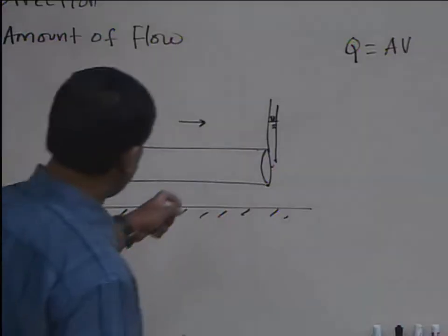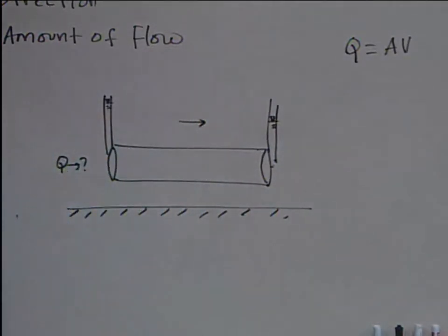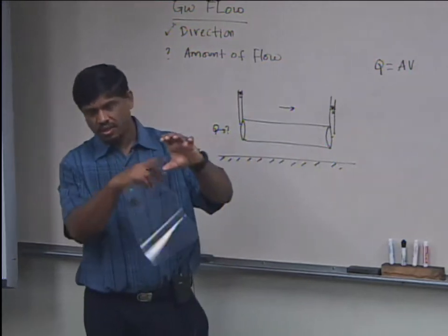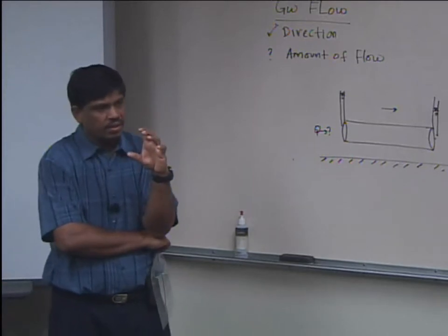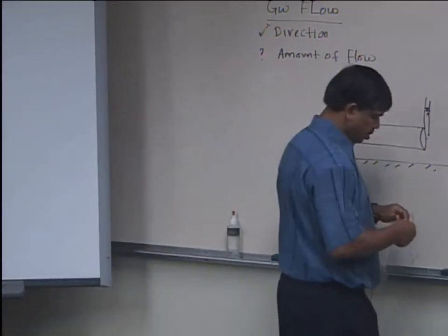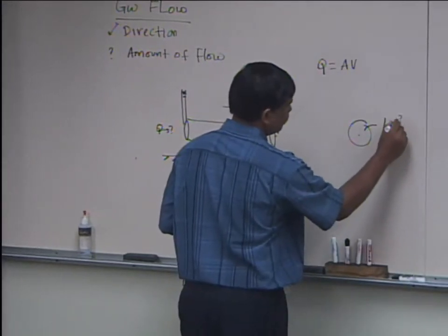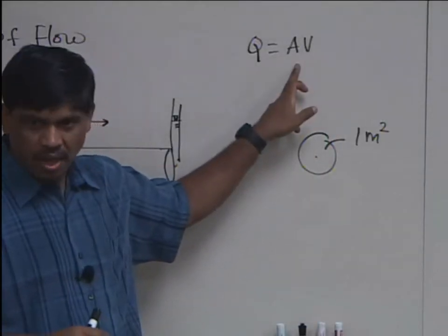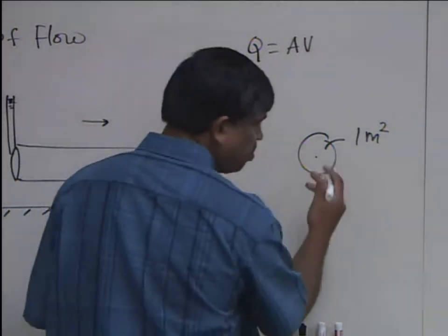What would be different from a pipe? Let's say I gave you a velocity. Let's say the groundwater is flowing with a velocity of, I don't know, 2 meters per day. How do I calculate A if it's a porous media filled column? Let's say the pipe cross section is 1 meter square. Can I use that? You need to account for the porosity, remember, because in the open pipe, it's 100% void.